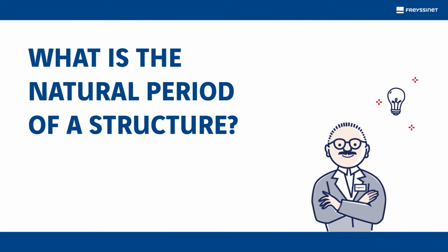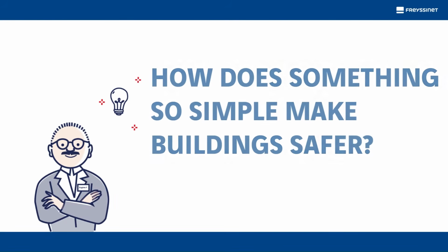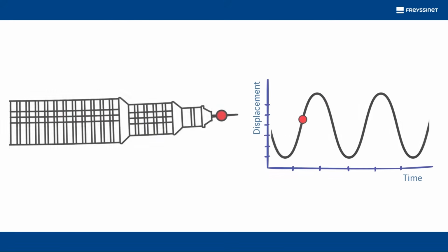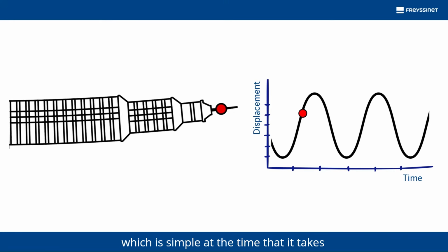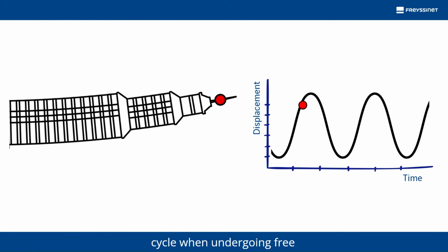But what is the natural period of a structure? How does something so simple make buildings safer? Every structure has a structural period, which is simply the time that it takes for a structure to complete one full cycle when undergoing free vibration.